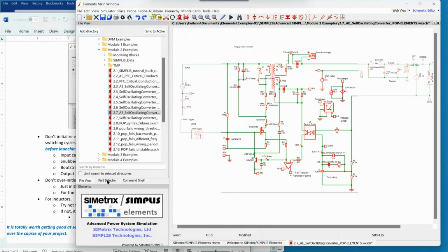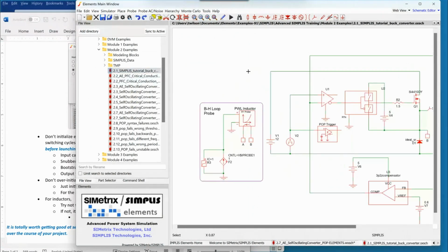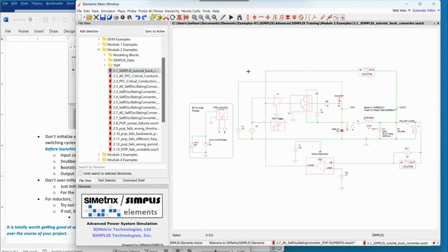And the current through the inductor, as solved by simplest for the initial condition, since we didn't specify it, may not be equal to 500 amps at all. It may be small, it may be large. Most likely it's up to 500 amps, or maybe small if the internal model of the controller is turning off that particular phase. So right at T equals 0, you have a big imbalance between the current through the inductor and the load current. As a result, the output voltage would drop until finally the controller model corrected.